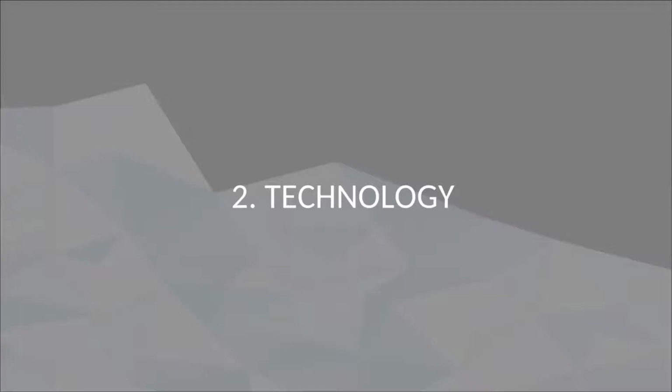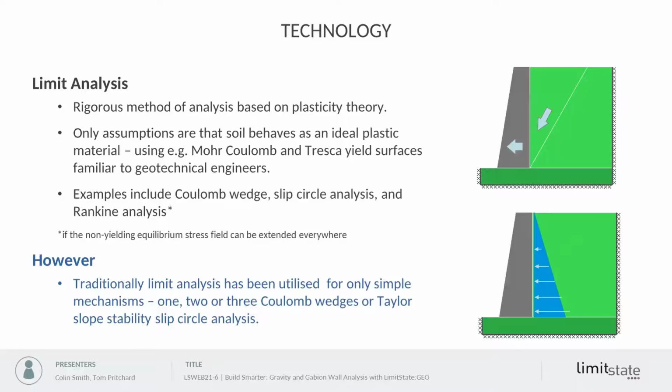Before we get into looking at Gabion walls and gravity walls, just a little background on the technology. If you examine standard textbooks and design codes, you see a broad consensus on the general principles of retaining wall analysis, which are adapted for specific scenarios. Typically a limit equilibrium approach is used. An analysis may be based on either a Rankine earth pressure distribution or a Coulomb wedge type analysis. And LimitState GEO is essentially an enhanced wedge type analysis.